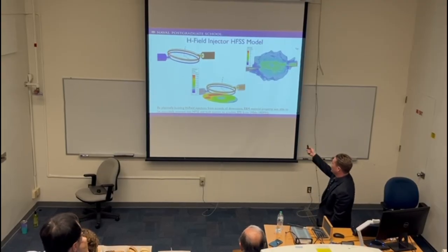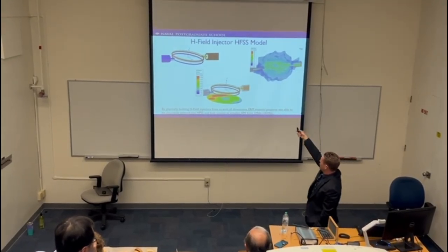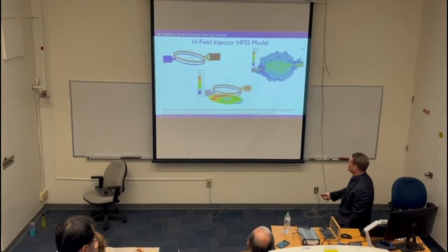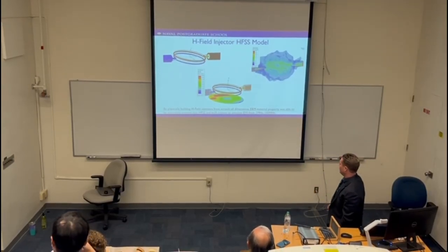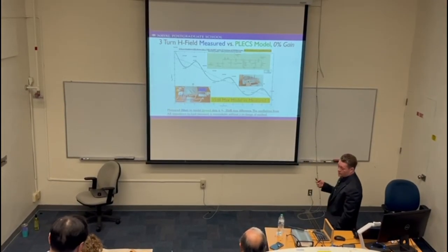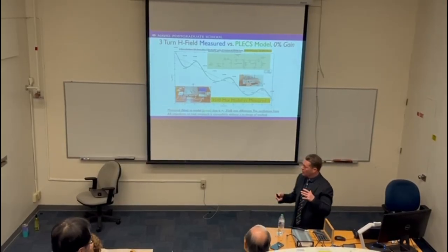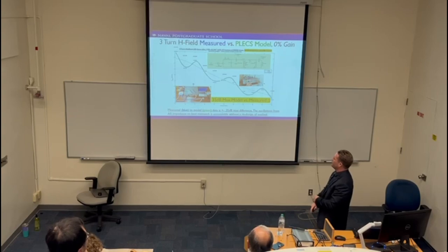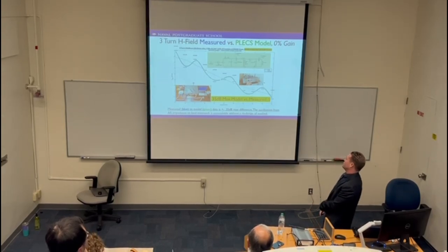my field here. And you can just see here, one of these is decibels of H field, another one is just absolute meter. And again, we simulated it from 1 megahertz to 100 megahertz. Here's the results. So this is back to the equivalent circuit model. This is the road that we focused on at first. As you can see here, very nice overlap.